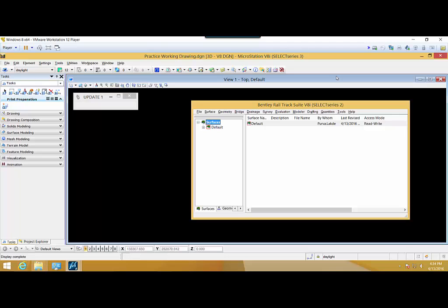The Bentley Railtrack will use this configuration until it is changed. The specific preference file will automatically be loaded when Bentley Railtrack is activated, and the folder location will become the default when using the File Open and File Save As command.